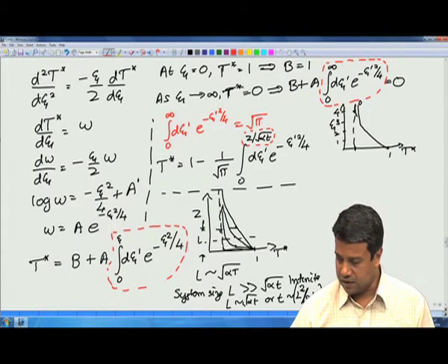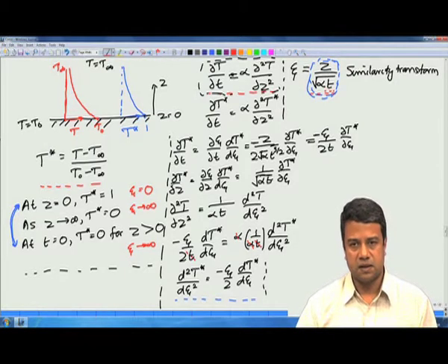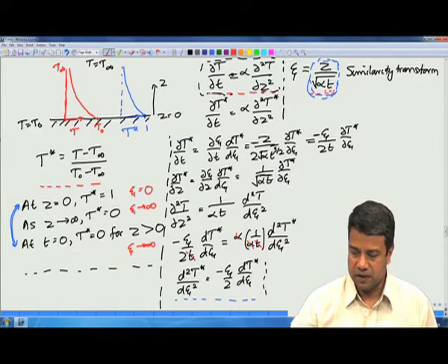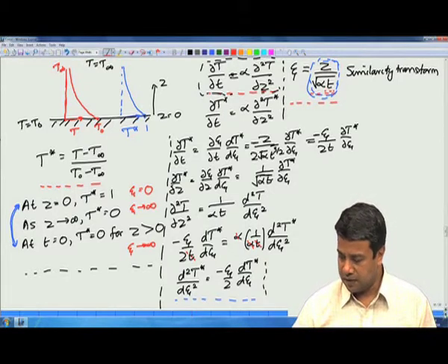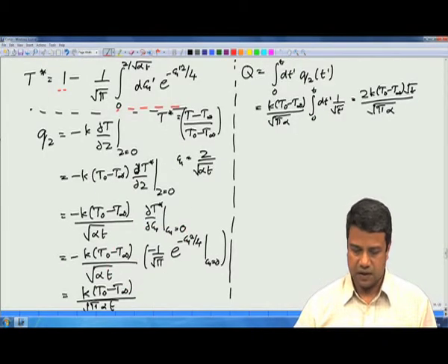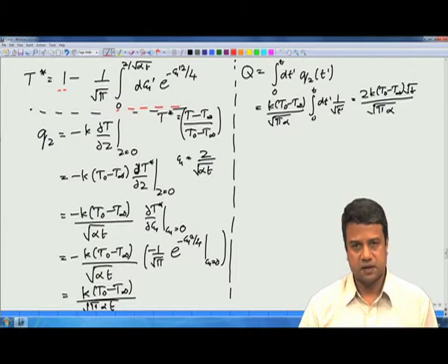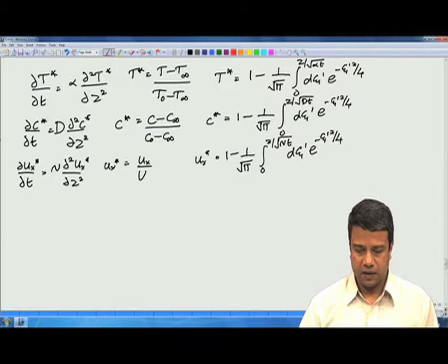And then we solved this equation using a similarity solution for this problem, because there is a deficit of dimensional parameters for scaling the length and the time scales, and therefore we were able to identify a similarity parameter. We got expressions in terms of the similarity parameter for the temperature field, the fluxes, the total transport rates. And these solutions were exactly the same whether it was for mass, heat or momentum transfer.